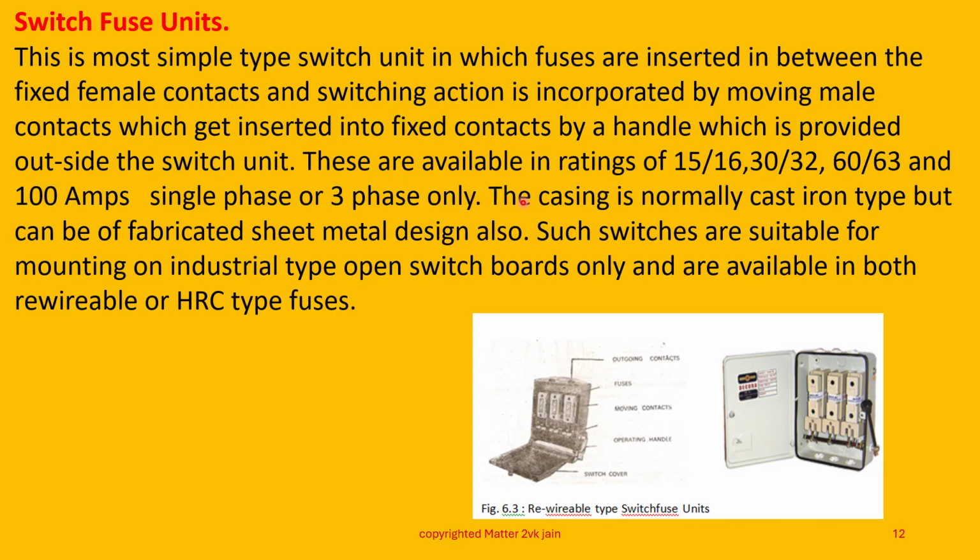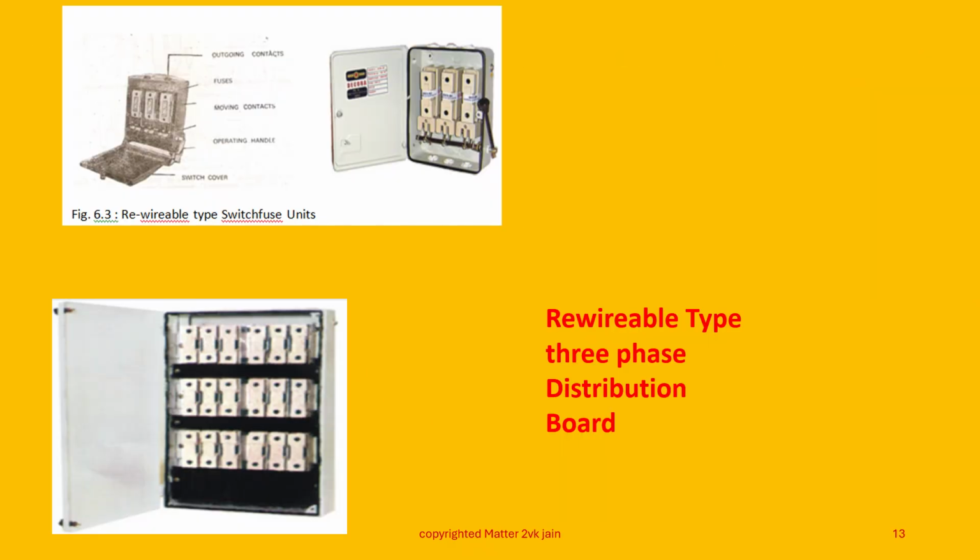The casing is normally cast iron type, but can be fabricated sheet metal design also. Such switches are suitable for mounting on industrial type open switchboards only, and are available in both rewirable and HRC fuses as shown here. Friends, we have already reviewed these rewirable type three-phase distribution boards.